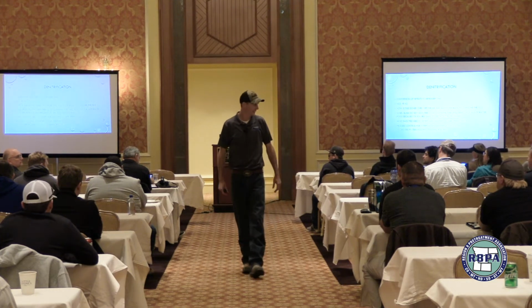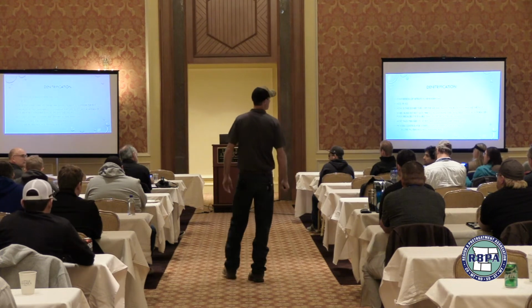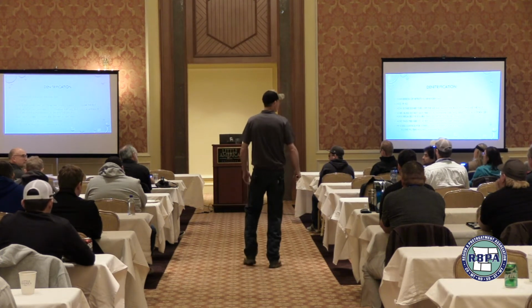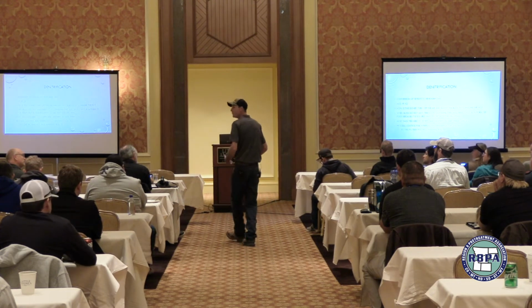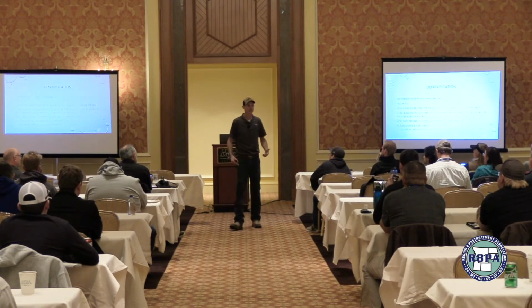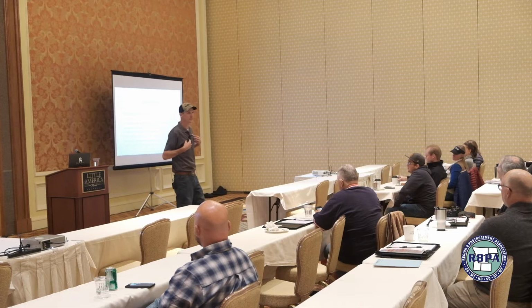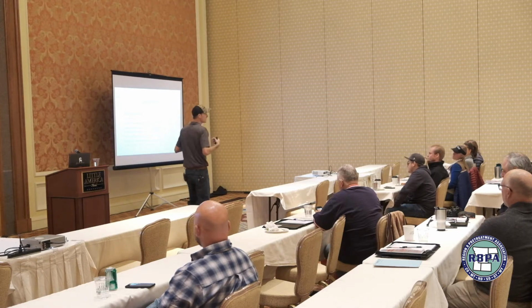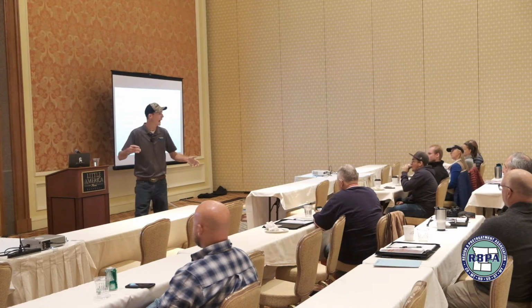It precipitates. What happens to your biosolids when you precipitate too many metals? You can't get rid of them. Now, is this all kind of making sense why this tall, nerdy guy is talking about wastewater plants? You guys directly affect what I do every single day. If you allow your local limit to be X for zinc or chrome or whatever it is, I need to know that.